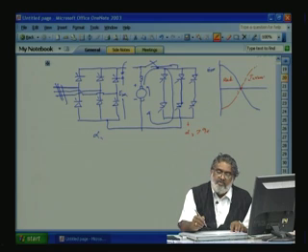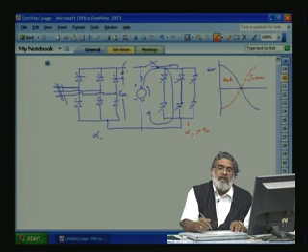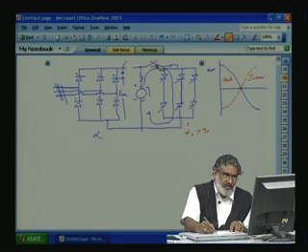But here the problem is that this is a slow process, because there are switches we have to sense and open and close. Okay. For fast control, the controller should be able to sense automatically, and the system should be able to, without this mechanical switch, send power back to the mains as well as receive it also. So, 4 quadrant operation. Instead of that, what is done, these switches are removed. So, let us remove the switches now.